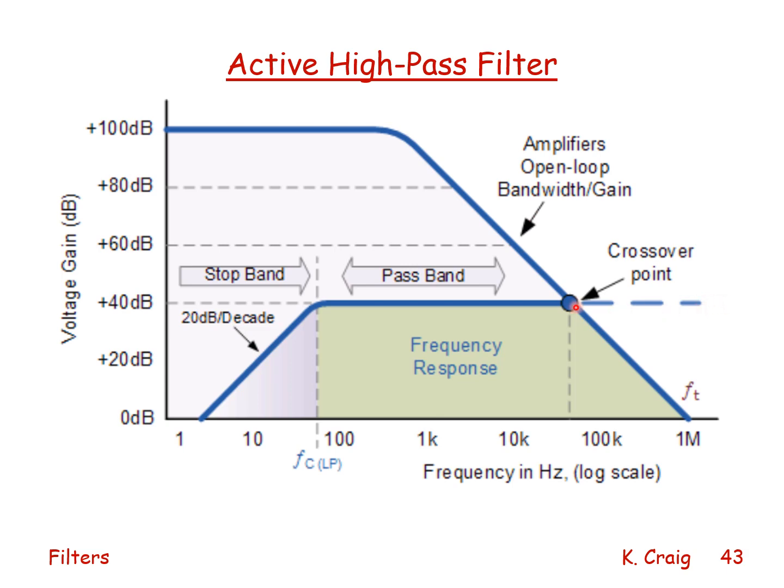It's limited by the op amp open loop bandwidth, and it then follows the curve for the open loop amplifier frequency response and follows this line down to 1 megahertz at 0 dB.